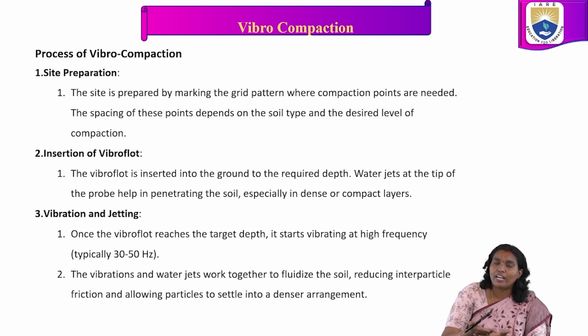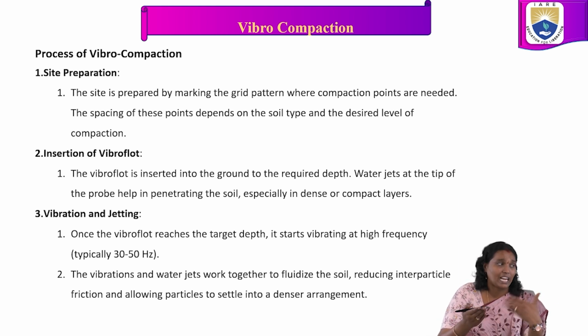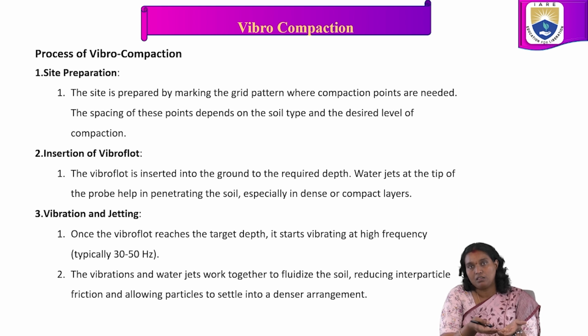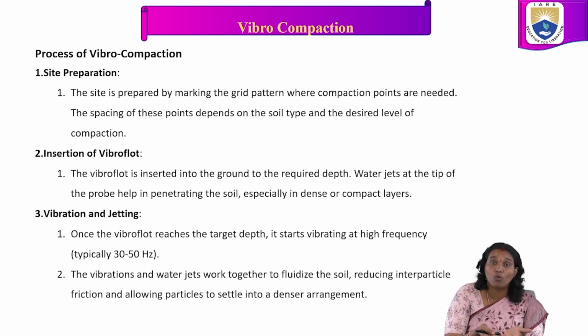What kind of water table is available there? Are any water tables available nearby? How much water jet is required for the vibro compaction mechanism, and for the internal vibration, how it performs based on the power supply or other energies and the efficiency of that equipment. These are all the parameters we have to understand in site preparation.